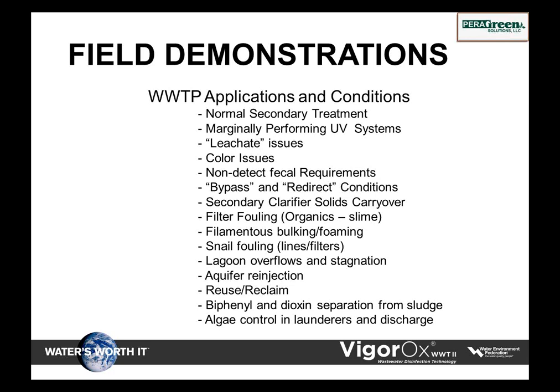So you have to understand, if you're feeding leachates, what is the background? One thing we're looking at is having to feed a sacrificial oxidant to overcome that demand before the PAA can do its job. So again, you have to understand all the dynamics involved in this process. It's not simply just applying the product and saying, okay, we're going to get the kill.